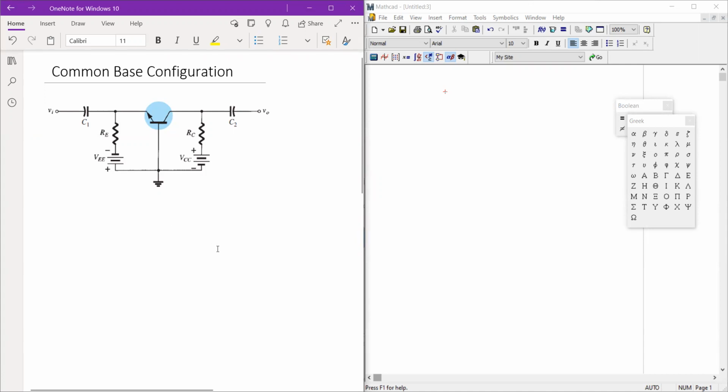On this session of bipolar junction transistor networks, we will cover common base configuration, DC analysis of common base configuration. Now with common base, for this configuration, as you can see, our base terminal is connected to our common terminal, or our reference, in this case, our ground. And again, this will become clearer why we refer to it as common base.